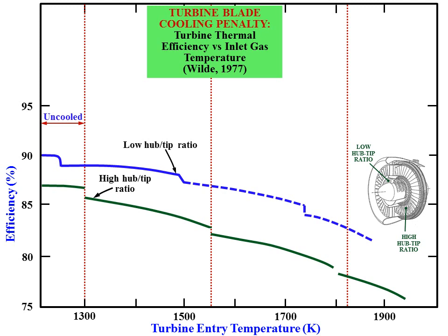For temperatures from 1200 Kelvin up to 1300 Kelvin, normally we will use the uncooled blade, as shown in the figure. So no holes for the cooling process.